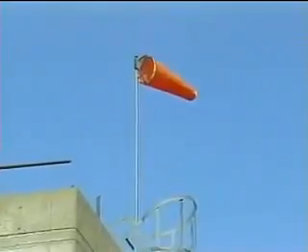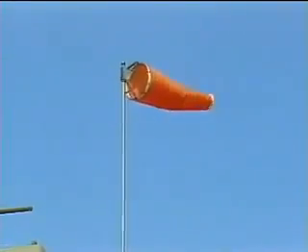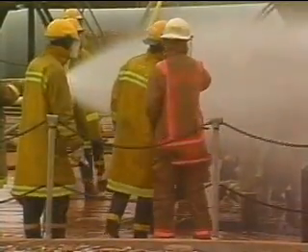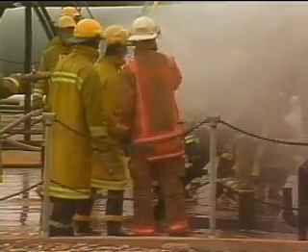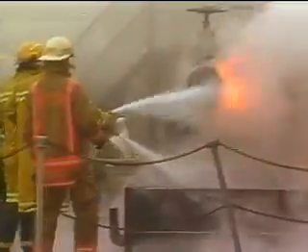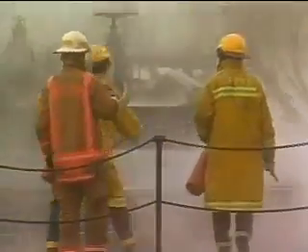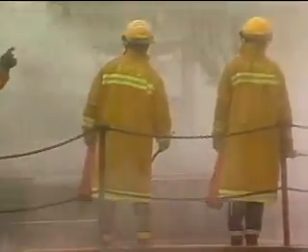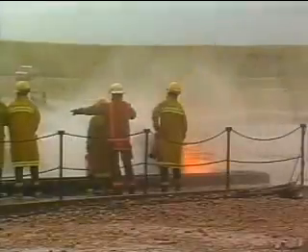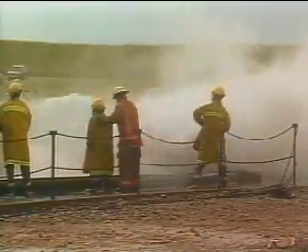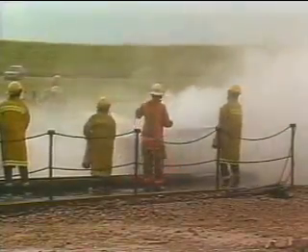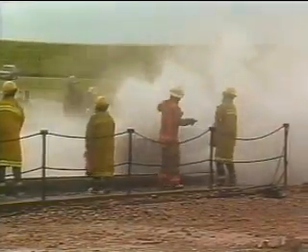When fighting a pressure fire, approach the fire from the upwind side of the fire. Direct the extinguishing agent at the fuel source first. Move the extinguishing agent down the stream of escaping fuel and extinguish any remaining fire by using a rapid side-to-side motion. In some cases, it may not be advisable to attempt to extinguish this type of fire until the fuel supply can be shut off.